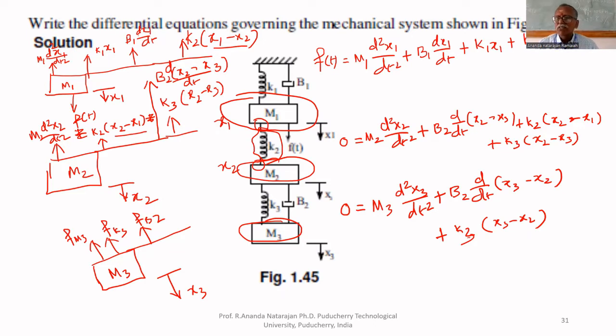Now after finding number of nodes, what you will do? One node will be taken as a reference. For remaining nodes, you will write KCL. Therefore, number of equations for KCL, current equation, Kirchhoff's current law, equal to number of nodes minus 1. If it is KVL, Kirchhoff's voltage law, number of equations equal to number of loops in that circuit, number of closed paths in that circuit.